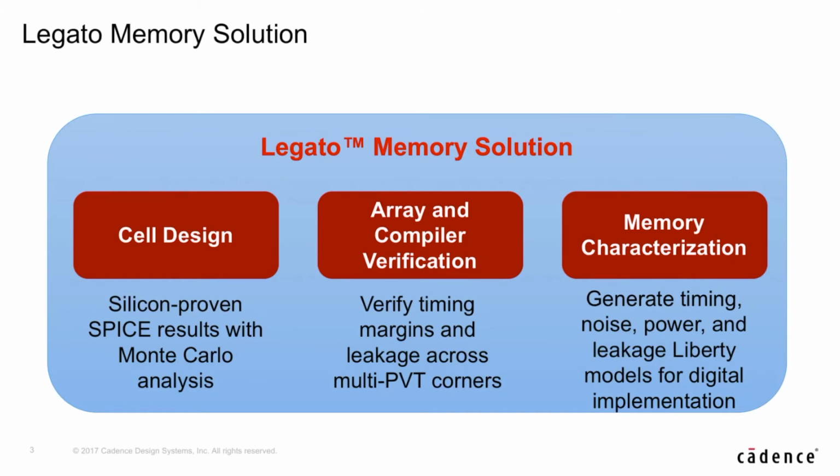And once you're satisfied with that, you move to the verification cockpit. In the verification cockpit, you verify the entire memory array, and you make sure the timing and the power are all meeting your design specification. After you verify and make sure it is accurately meeting your spec, most likely you need to create a .lib format of that memory array that you have just verified.